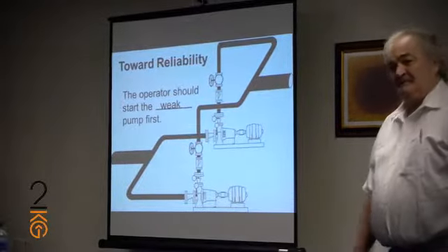These are parallel pumps. Both pumps are turned off. You're going to start these pumps. So the process engineer says to the operator, I want you to start those two pumps. Which pump do you start first? The operator should start the weak pump first.